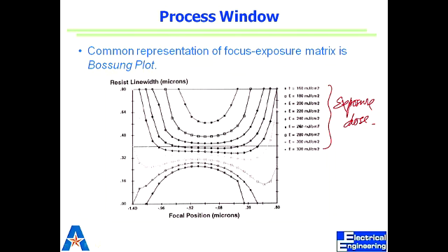The middle line, that straight line, what is that? That's the axis. That is just a line to show the flatness of this axis here. Right? Because if you don't have that, you would think this is straight, but this is changing. So the Bossung plot is important to figure out focus, exposure, and process window.